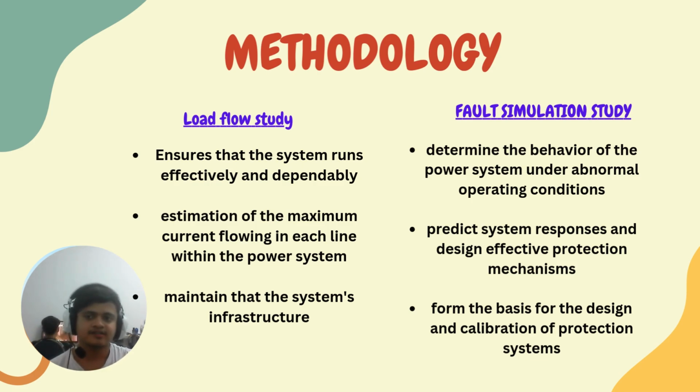The following faults to be analyzed are single phase to ground, line to line, double phase to ground, and three phase to ground. From this simulation, it is possible to identify the peak and the minimum value of the fault current. The fault simulation study also provides insight into the system resilience and possible impact on the power quality and stability.